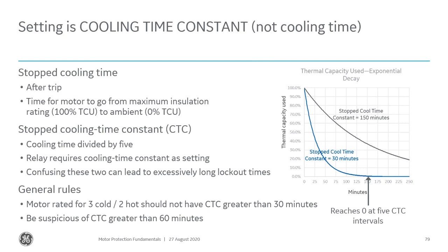General rules: if your motor is rated for 3 cold and 2 hot starts per hour, you should not have a cooling time constant greater than 30 minutes. And you should be suspicious of any cooling time constant greater than 60 minutes.